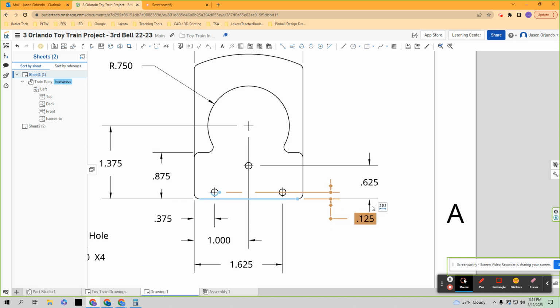But this right here would be confusing because that 0.125 is right next to this little arrow and somebody might get confused. So if it's going this way, I certainly need to create some distance to make it a little more obvious that that's going here and not here.